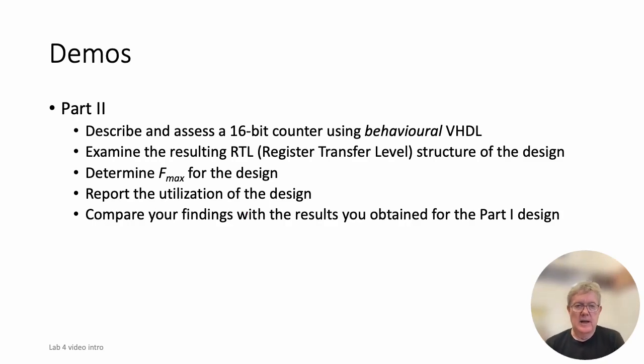For part 2 of the lab, you're going to compare the structural design of the 8-bit counter you created in part 1 with a 16-bit counter that you're going to implement using behavioral VHDL. So in this design, you're going to be incrementing the count value in a behavioral description of the counter.